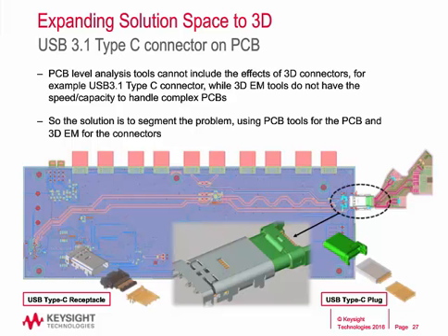So the solution is to segment the problem, applying PCB problems to PCB tools, and connector transition problems to 3D EM tools. With this approach, connector to PCB transition to FEM and PCB to SIPro, we can increase the analysis speed dramatically without losing much accuracy. But this has to be done carefully.